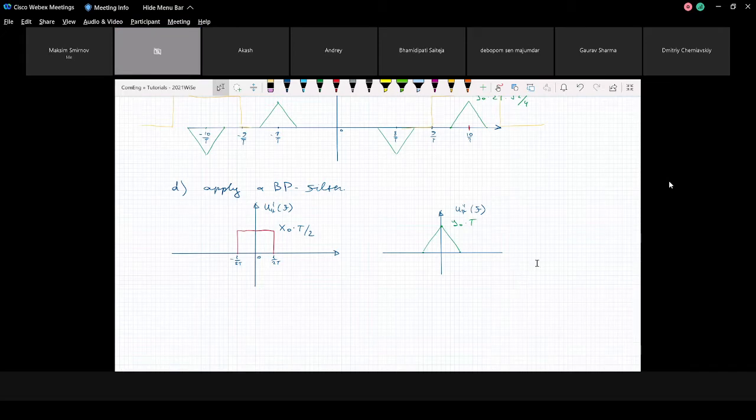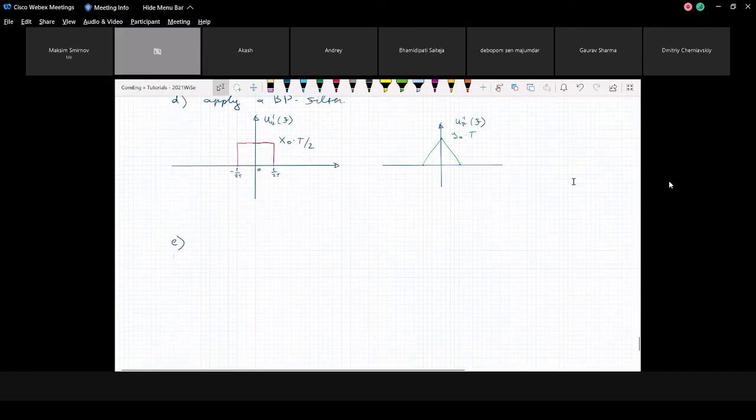I think that's all for this part D. Then we go to part E. So at part, not E, part E was for this transformation. Now we go to part F. So the approach treated so far is called superheterodyne up conversion. Which steps are required for superheterodyne down conversion? Assume that the spectral range below 9 over t may also contain spectral components due to noise, neighboring channels, and so on and so forth.